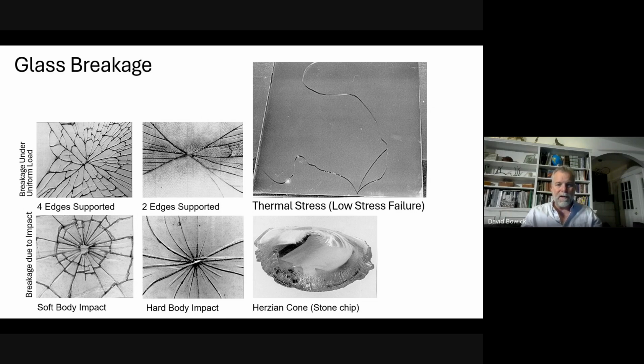And his answer was, "It's unpredictable. You don't want to burden your whole building with heat strengthened glass because of the possibility of a thermal failure. What you do is you use regular glass everywhere just to conform to the building code. If you get a thermal failure, when you replace the glass, use heat strengthened, because now you've identified a condition that's vulnerable to a thermal failure." Okay.